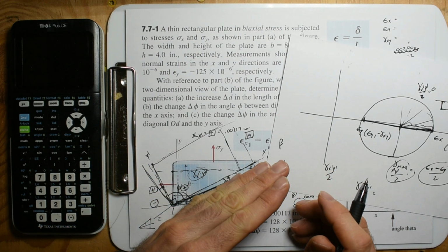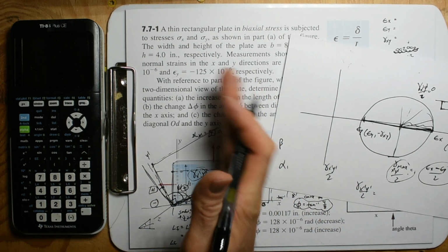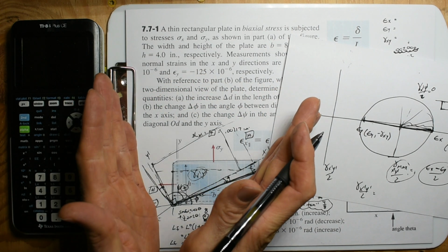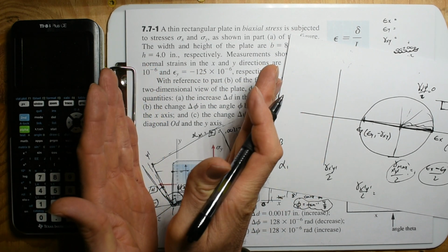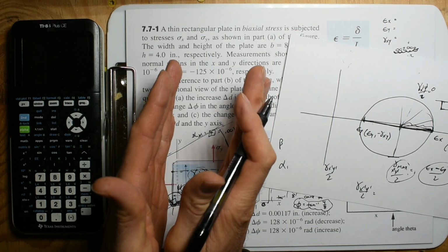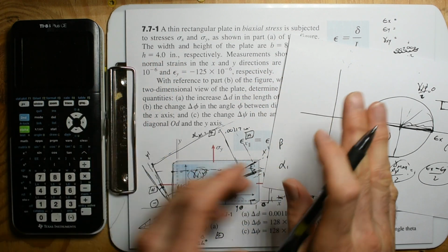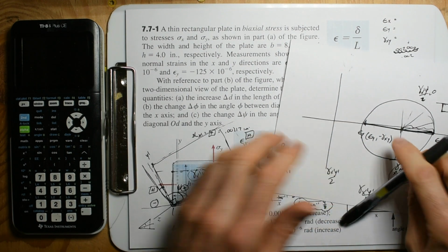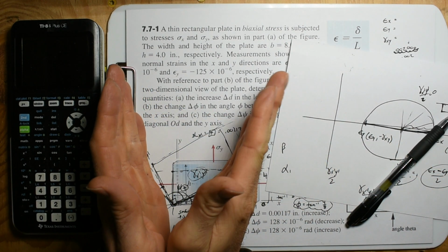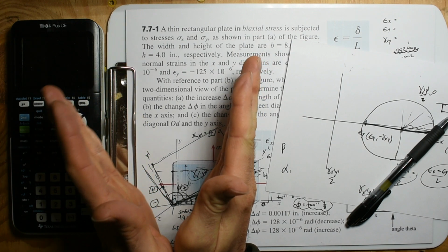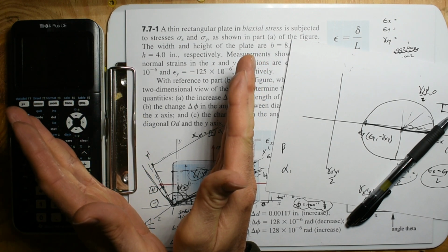The textbooks will always say that angle is going to be positive with the right-hand rule, but we know that they have to couple together. If this angle goes this way and that angle goes that way, that's going to be associated with positive shear. If they broaden out, that's negative shear. And so the textbooks have to say this is positive alpha, cool, for positive shear, but this is going to be positive beta, and we have to subtract it.